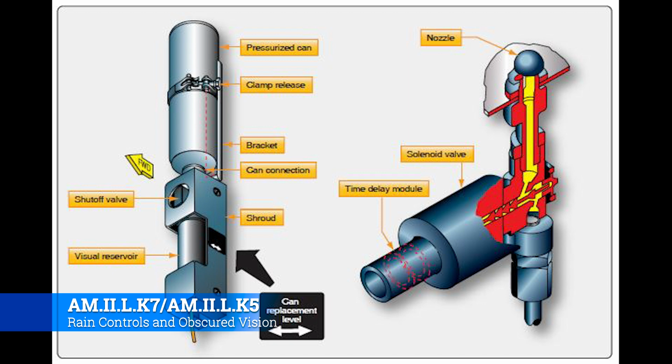Now, however, the thing to keep in mind is that there's not a lot of fluid in there, so it's not going to last too long. And so it's one of those things that you only really want to use whenever you absolutely are ready to land, or you're looking for traffic, or whatever the thing is. So just kind of like TKS, only use it whenever it's time to use it, and for as short a time as you can get by with.